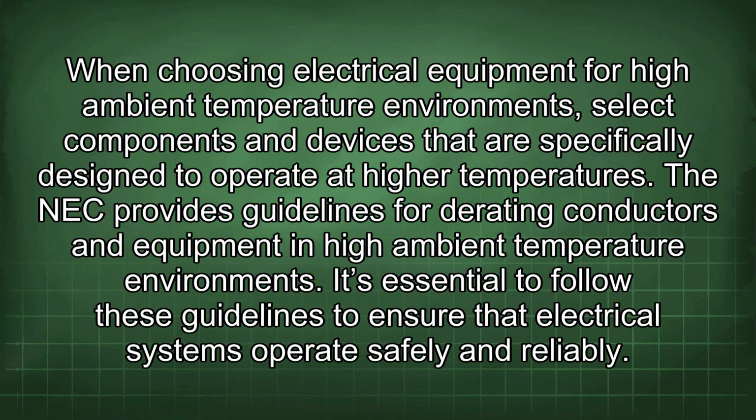When choosing electrical equipment for high ambient temperature environments, select components and devices that are specifically designed to operate at higher temperatures. The NEC provides guidelines for derating conductors and equipment in high ambient temperature environments. It's essential to follow these guidelines to ensure that electrical systems operate safely and reliably.